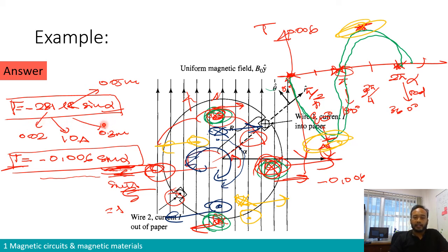Next week, we are going to look at the calculation of force and torques in electrical machine as well, but not using the Lorentz force law. We're going to use what we call the energy method. Instead of going through the equation of Lorentz force law, because not all machines are as simple as DC machines. Other machines are more complex, where we have more conductors and they are not always continuous current like here. For example, here we have the current which is continuous, I equals 10 amps. We might have variation of currents which is not necessarily DC and not as simple as this one.